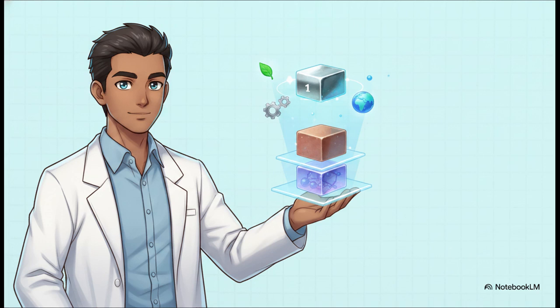Once we've shortlisted the survivors, we rank them, and this ranking is driven by our objectives. Which of these surviving materials minimizes mass the best, or maximizes strength the most? But it doesn't end there. Step 4 is supporting information. The top-ranked candidates get evaluated against practical, real-world facts. Is it actually available in our region? Is the cost within budget? Is it eco-friendly? Can we even process and manufacture it easily? The winner of all 4 steps, they get the job.